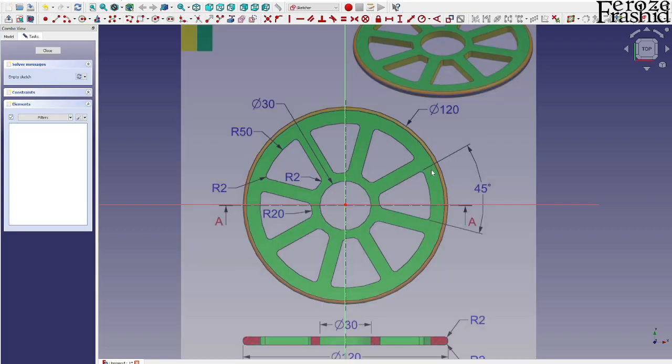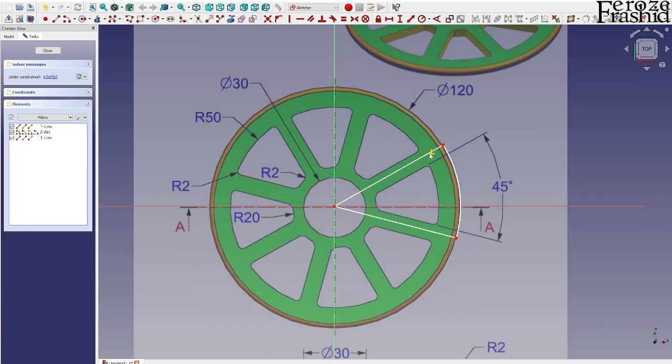I want to do this basic part, and let's go ahead and signify our boundary, and I want to say this is going to be an arc there. Okay, so these 2 points will coincide with each other. I want to take this constraint off. Now the angle between these two is given as 45, but let's go ahead and see what would be this angle.